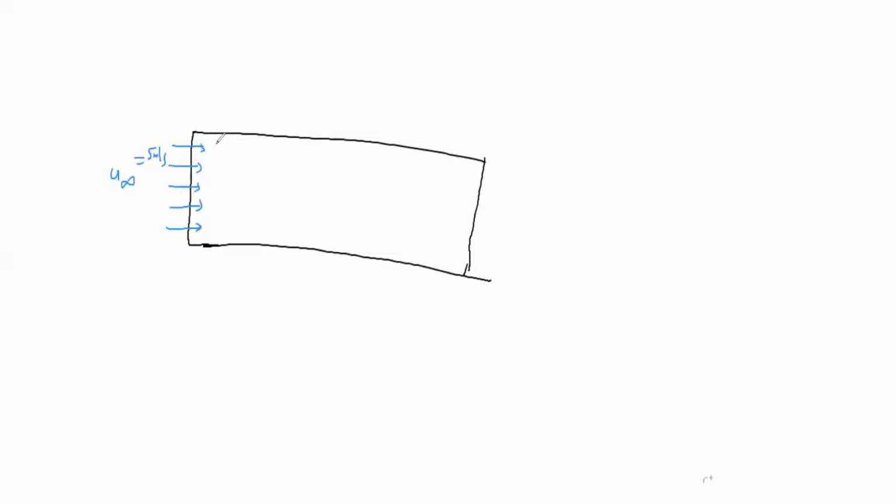It is 0, which is affecting the other layers of the fluid. And that is why you are getting a parabolic profile, correct? Here it will be 0, then it is slowly increasing, and at the center it will be maximum, and again it is slowly decreasing as it moves towards the wall. So near the wall we provide no slip, which makes sure that near the wall velocity is 0, so that we are able to capture this physics.